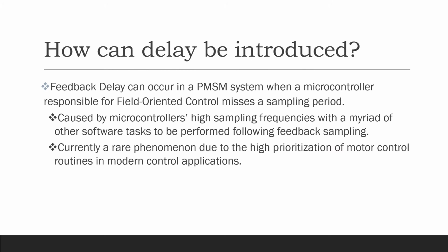So how is delay introduced? What is delay? Why does it matter? Feedback delay can occur in a PMSM system when the microcontroller that is responsible for performing the field-oriented control on the motor misses a sampling period.